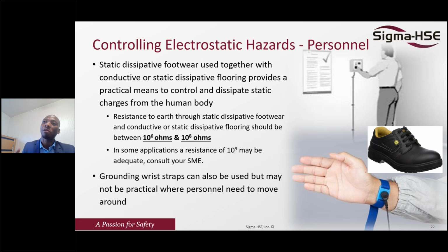Having static dissipative shoes actually is not enough. You need to ensure that the flooring where you stand is also conductive. Normal cement is conductive, or you can paint it with a static dissipative material, or you can have a static dissipative mat. For ergonomic purposes, excellent. If I'm a worker who stands at one place, I'll tell you I need a static dissipative mat, which has a cushion and ergonomically it's really, really good.